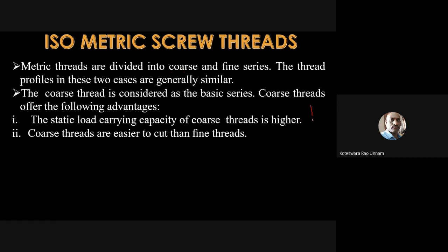Cutting 10 threads is somewhat difficult or complicated compared to cutting only 2 threads within the given length. Therefore, coarse threads are easier to cut than fine threads.